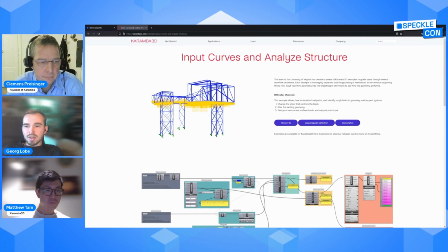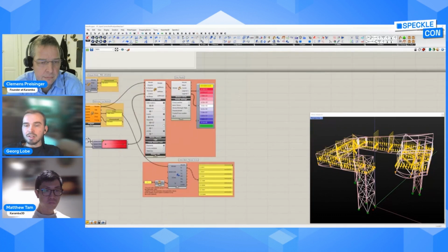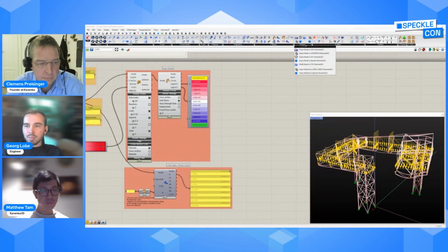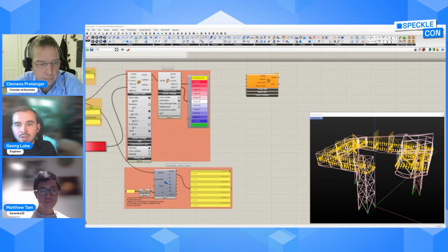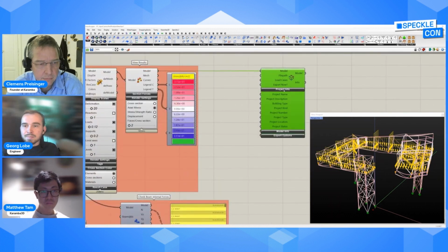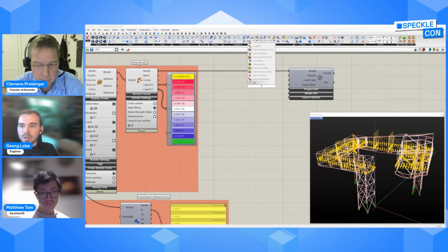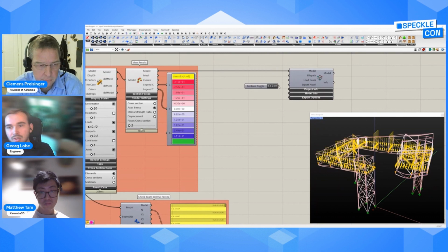The first thing I want to show you is the SAF export. You can find the component at the Export tab, and you also have to enable the Show WIP components. You have a lot of export options. You can add information to the model. The default export path would be your desktop with a default name, which is Karamba3D model.xlsx.